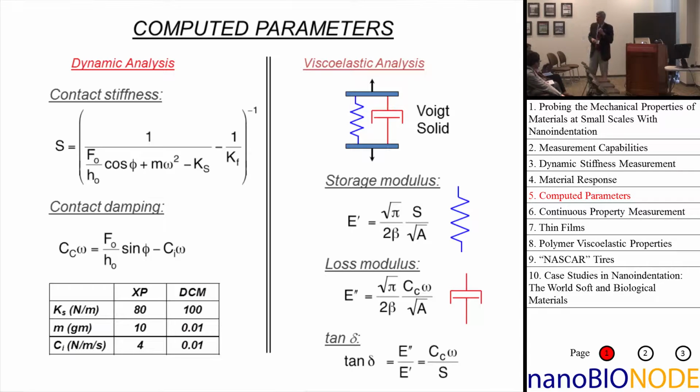But these calibration parameters are not changing based on the specimen, because machine parameters could be non-linear depending on the specimen. We're trying to separate out the machine parameters from the specimen parameters. The machine parameters will depend on things like the position of the indenter.